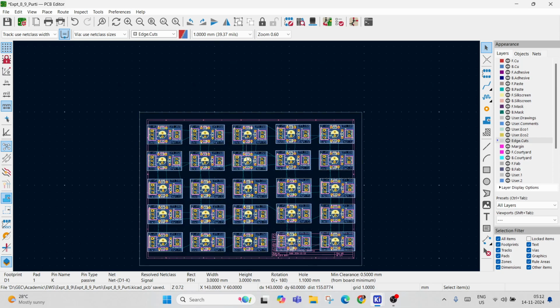Okay, so now that the PDF is generated, I don't need all of this. Now we are going to be generating the Gerber file in order to convert it to G code. There are two kinds of Gerber files. Back copper was for etching, so we have handled the back copper PDF for etching, whereas the Gerber file, the edge cut Gerber file and the drill hole file are going to go for G code.